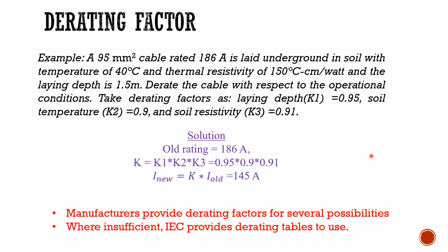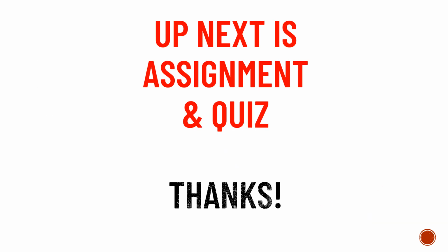Manufacturers provide the rating factors for several possibilities, so a cable comes with all these factors. But where insufficient, there is an IEC standard for choosing the rating factor of anything you want. There are tables that IEC provided for several conditions, and the rating factors.